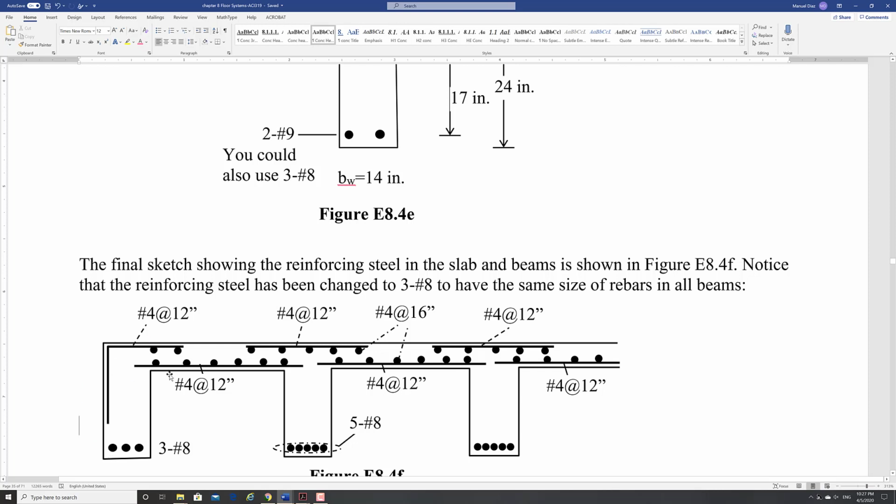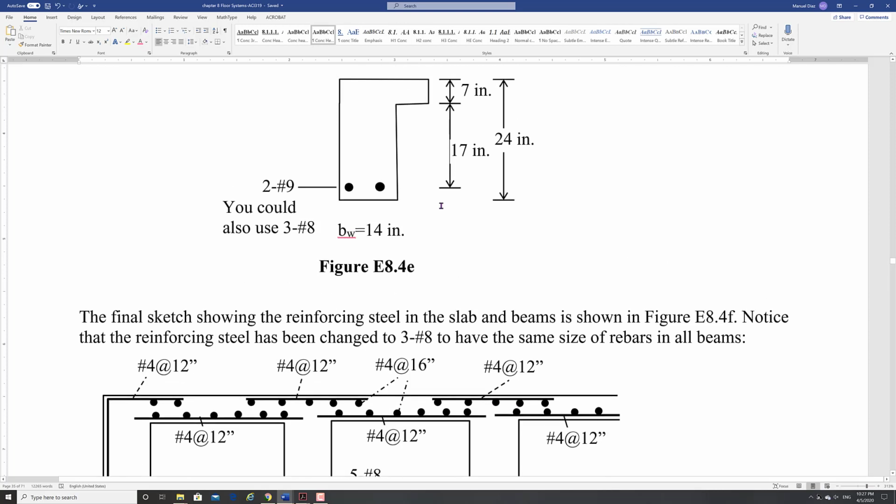In buildings, we seldom extend the slabs. We don't widen the slabs, and so this is okay. You should do that because there is less moment here. In bridges, you have a slab like this. You want to keep the same value that you got here. You want to put it here because in bridges, you may extend that as traffic increases, right? And so it becomes an interior, and so you want to have that, okay? Just for the future. But that's one way of doing it.